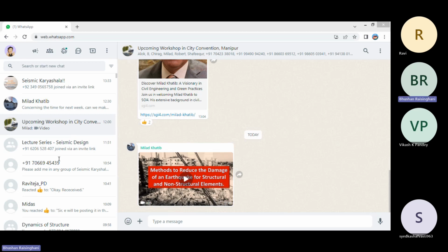Boundary elements, where required as per this, shall be provided with special confining reinforcement throughout their height. So throughout the height you need to provide your special confining reinforcement as defined in section 8 for stirrups of circle or rectangle. It is 0.05 Sv h fck upon fy, where Sv is the vertical spacing and h is the depth of the boundary element. So you will get the horizontal stirrups.